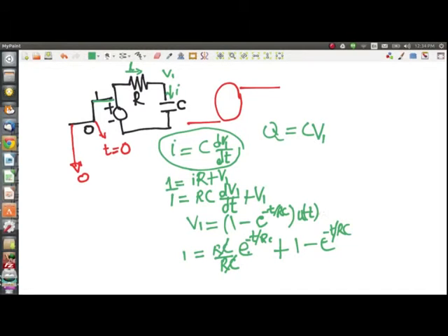So this is what the voltage looks like, which basically is an exponential characteristic here, which means only at time t equal to infinity will this actually become 1. So technically it never charges, but that's not interesting. It's charged enough after even 1 RC time constant. This is called a time constant because it has the same dimensions of time. E power, this has no dimensions, this is time, this is also time. So if you multiplied R and C, you would get something that we call a time constant, and as soon as it is 3 time constants or 4 time constants, you say it's settled enough.